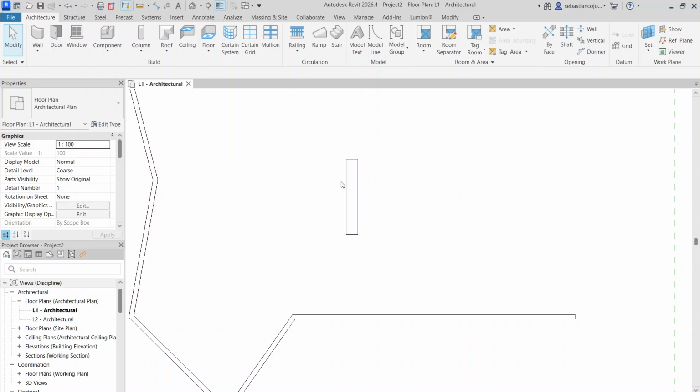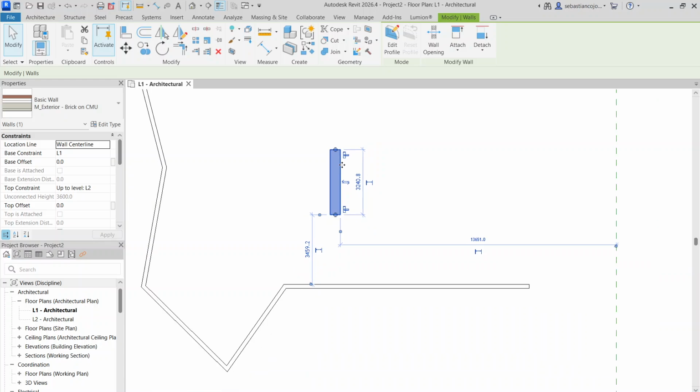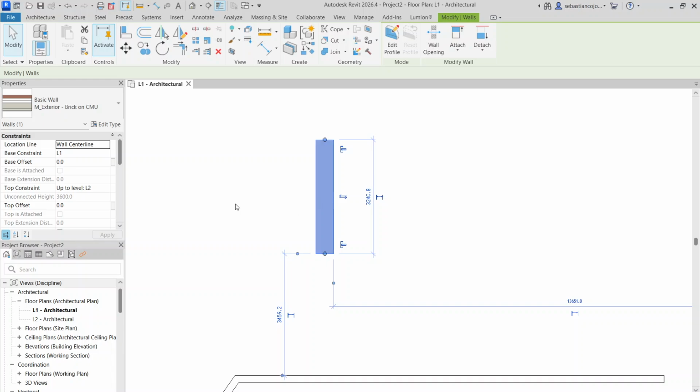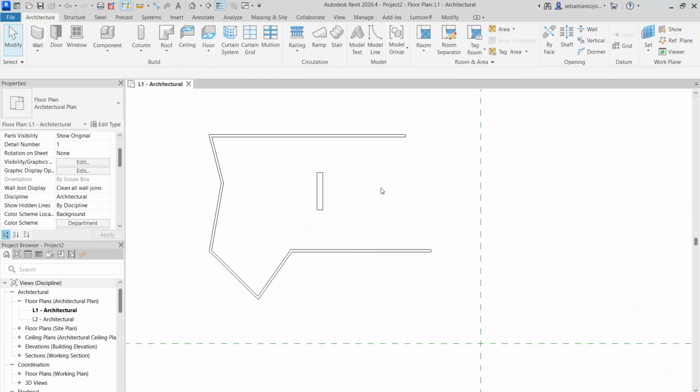And in another tutorial I'll show you, because if you have more stories, you can put between L1 and, let's say, the 7th story of the 20th if you have a tower. But for the time being, this is what you do with a wall. And it has an automatic height set, but you can modify it, but that makes subject of another tutorial.